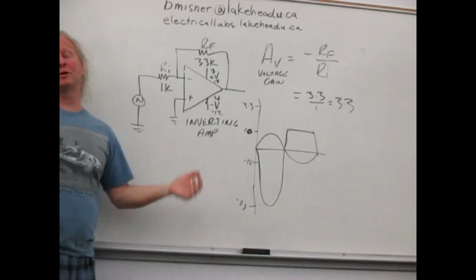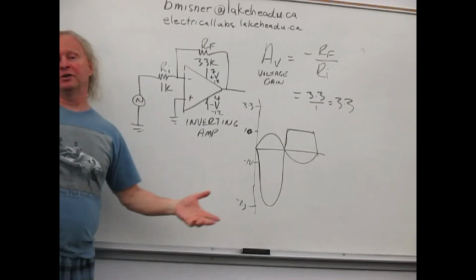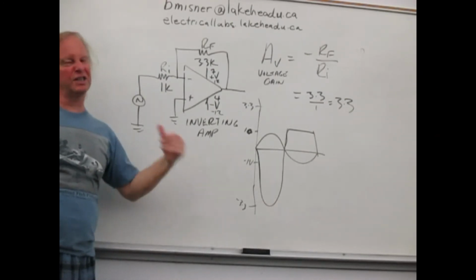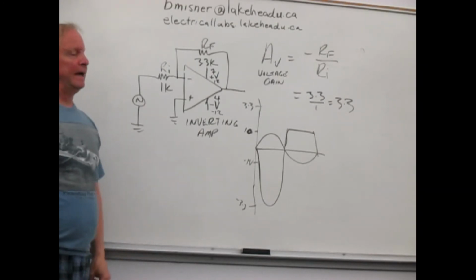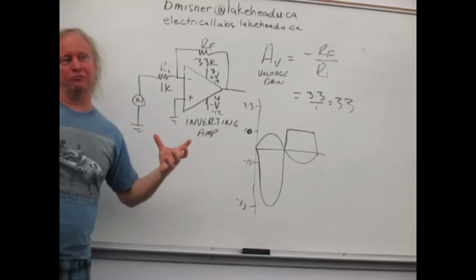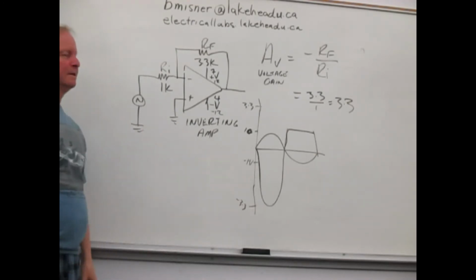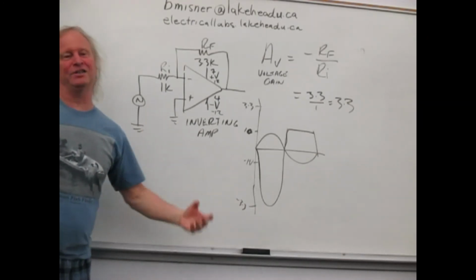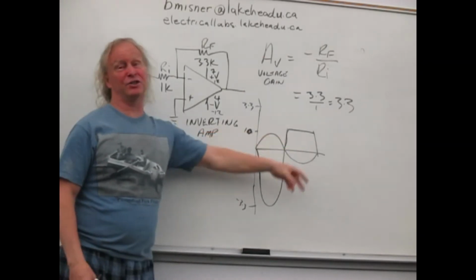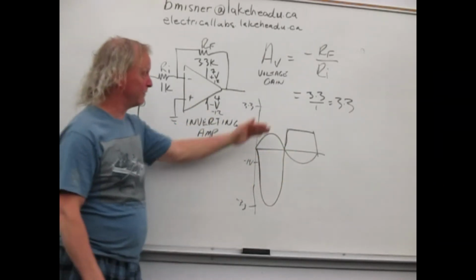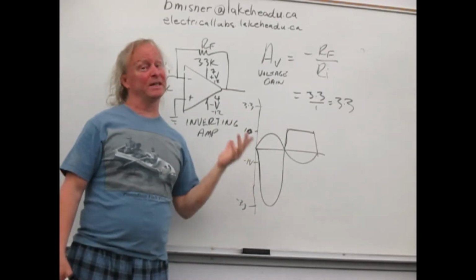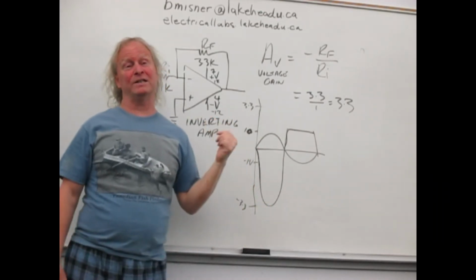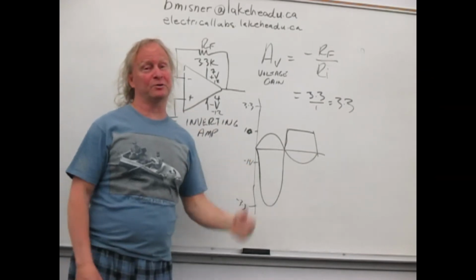Say if you were doing this on your amplifier at home, you're listening to AC/DC, you want to crank it right up. And then you crank it up and it sounds really raunchy and crazy. Well, actually it's getting distorted, because what you've done is you're clipping the signal off. And it might sound better, but I'll tell you something, it's not better, because you fry your speakers by doing this.